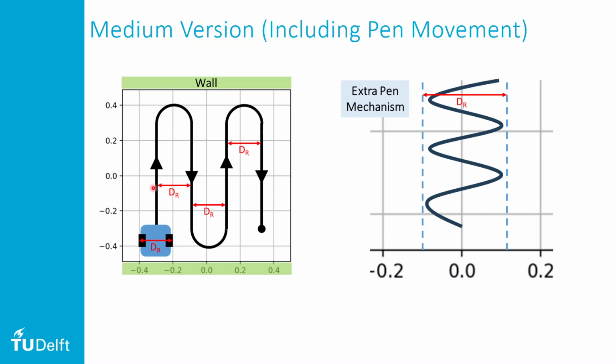Notice that the ideal distance between the two straights, dr, is the diameter of the robot. What that means is that you can do this turn by just stopping one of the wheels and driving the other wheel, because if you stop the wheel on this side, then the robot will do a turn sort of centered on that wheel, the pen's in the middle, and so we'll go from the robot being like there to the robot being there. Yeah, so I intentionally made that the distance I'm asking for because it makes it a bit easier.